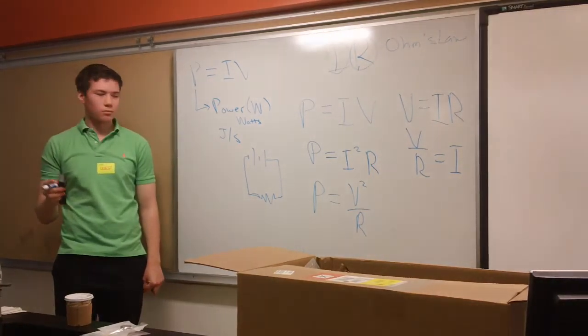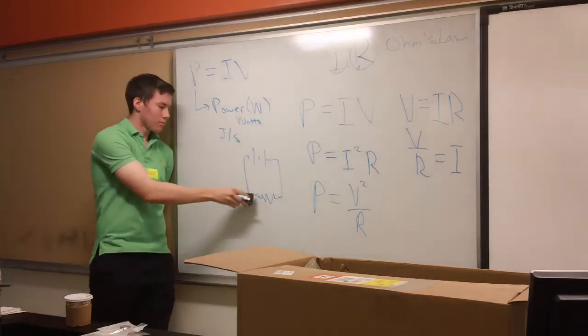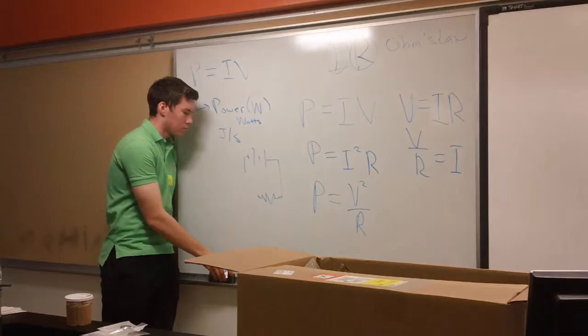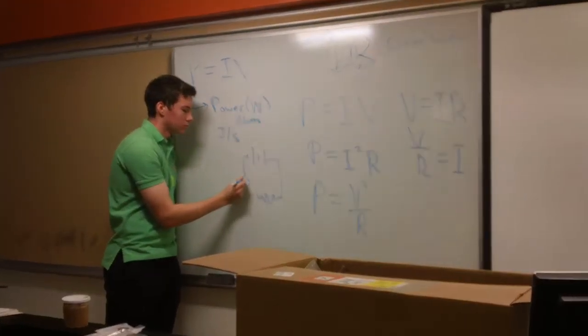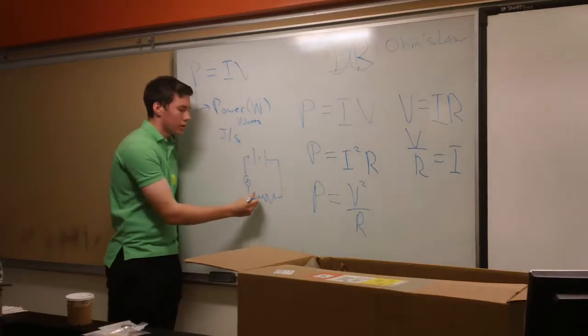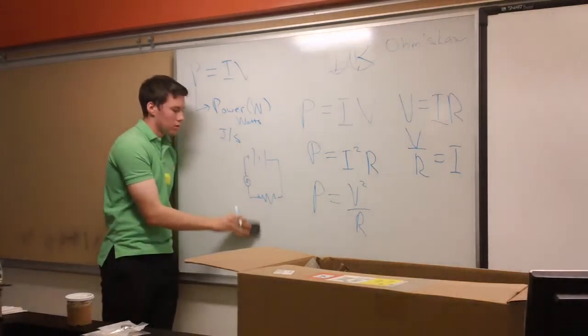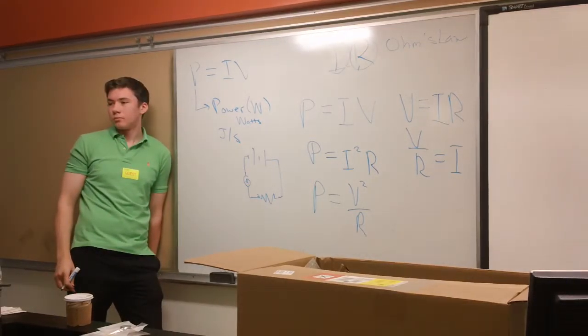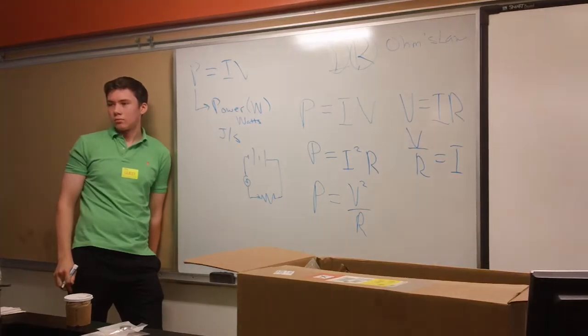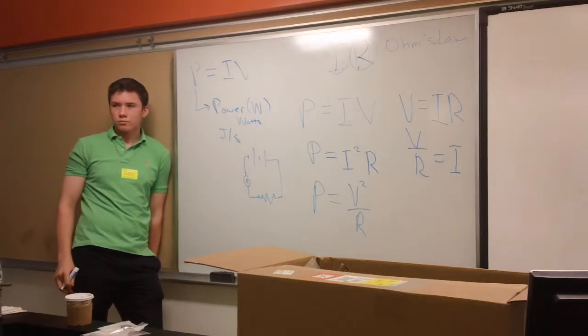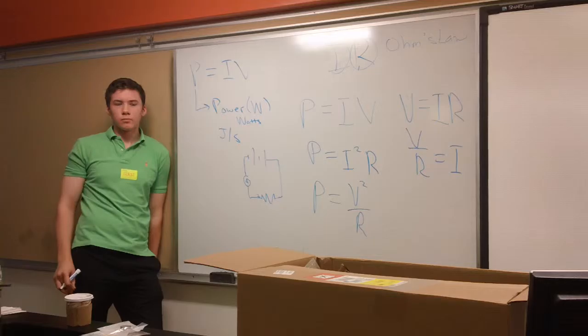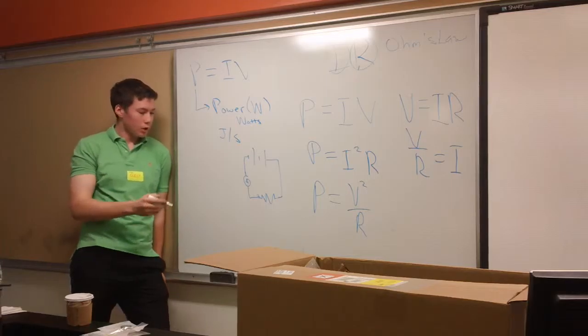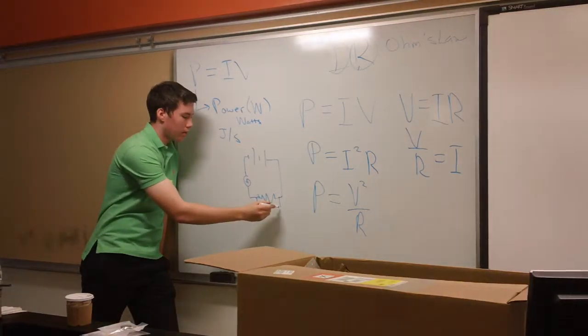You disconnect a part of the circuit, I guess, and then you attach it right in between, just like it's one point on the circuit. Why do I do it like that and not like this with the voltmeter? Because otherwise you would short it. Right, because what's the difference between an ammeter and a voltmeter? The ammeter's resistance is much lower. So if you connect the 2 points, the circuit is going to run through the least resistance, so you're going to burn it out. So the important thing is, if you're measuring the voltage, you put it in this configuration, which is known as parallel.